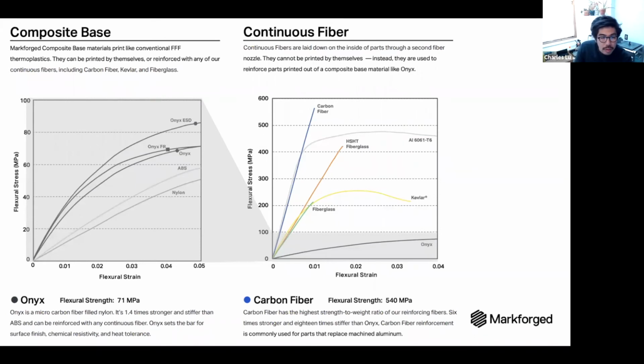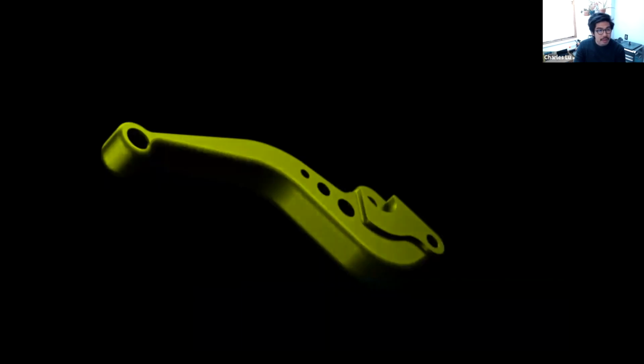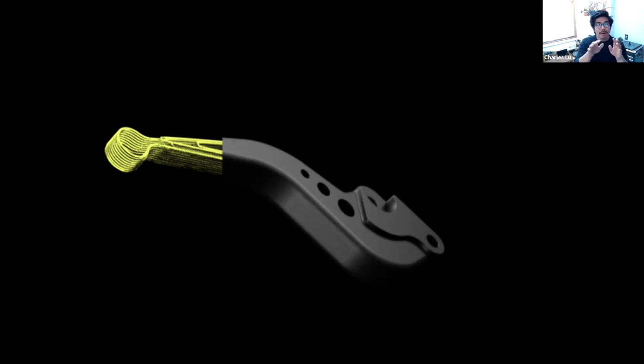Wear resistance. So that's Carlos, that's a great question. Wear resistance is improved by short carbon fibers. So the long strand carbon fibers are within the part, right? So you're not going to see that be, let me back up some slides here. So the long fibers are within the part. The short fibers are on the outside, and those actually do improve wear properties. So that applies to all nylon carbon fiber materials. It bears a lot of that load instead of it rubbing on the plastic. Although nylon on its own is already very wear resistant. So the combination of nylon and carbon fiber, very wear resistant, very impact resistant.